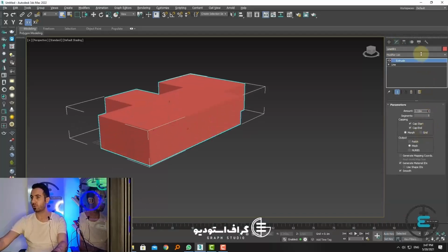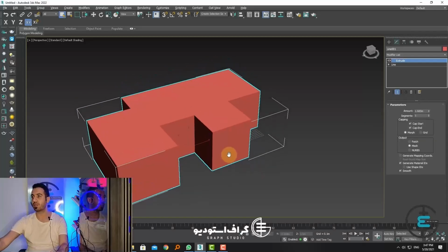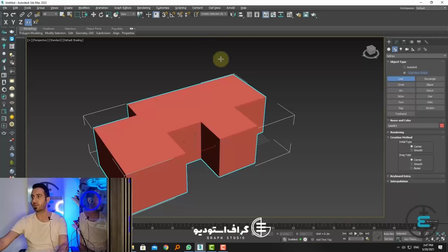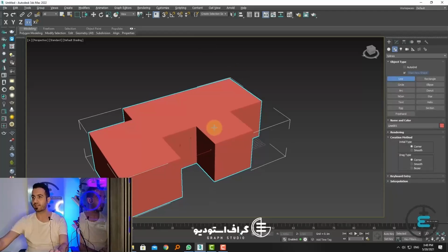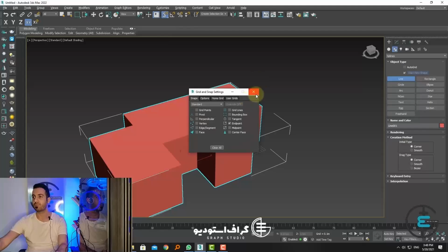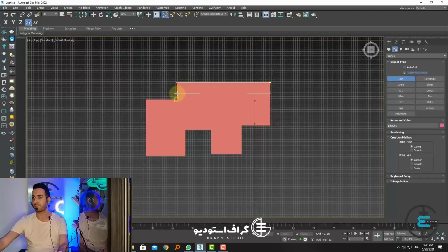Only, guys, let me mention an option here that I remembered. I activate snap. Well, I put it on 3D snap once, and I draw this in this way. Well, you see what has happened when I was drawing this. Because it is on 3D snap, in some places where there are two heights, it sees a height here, a point in, I don't know. When it is on 3D snap, unfortunately it suffers from such problems, meaning some of the nodes it detects up here and some of the nodes it detects at this lower point.